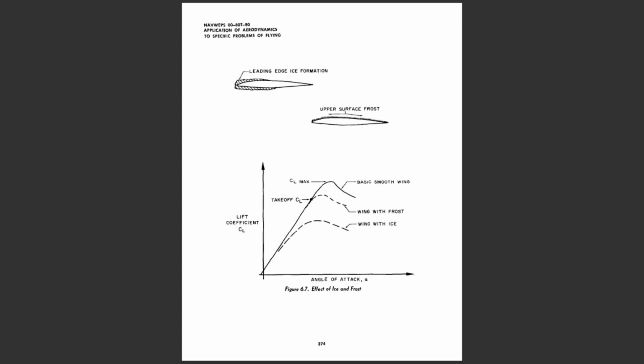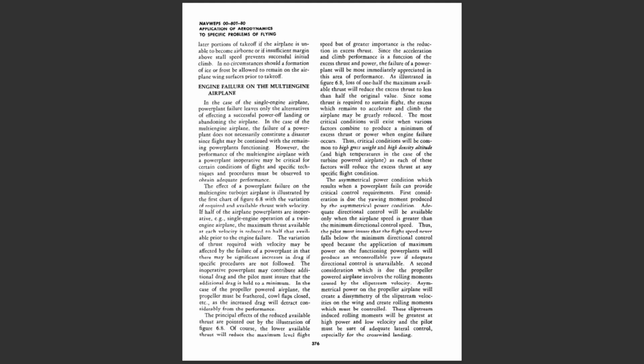Thus, the effect of frost or ice will be most apparent during the later portions of takeoff if the airplane is unable to become airborne or if insufficient margin above stall speed prevents successful initial climb. In no circumstances should a formation of ice or frost be allowed to remain on the airplane wing surfaces prior to takeoff. Engine failure on the multi-engine airplane.